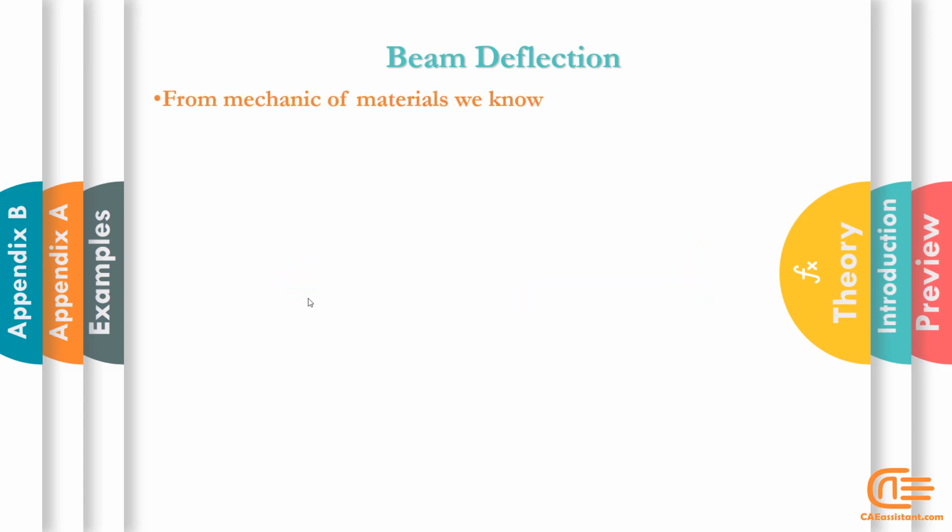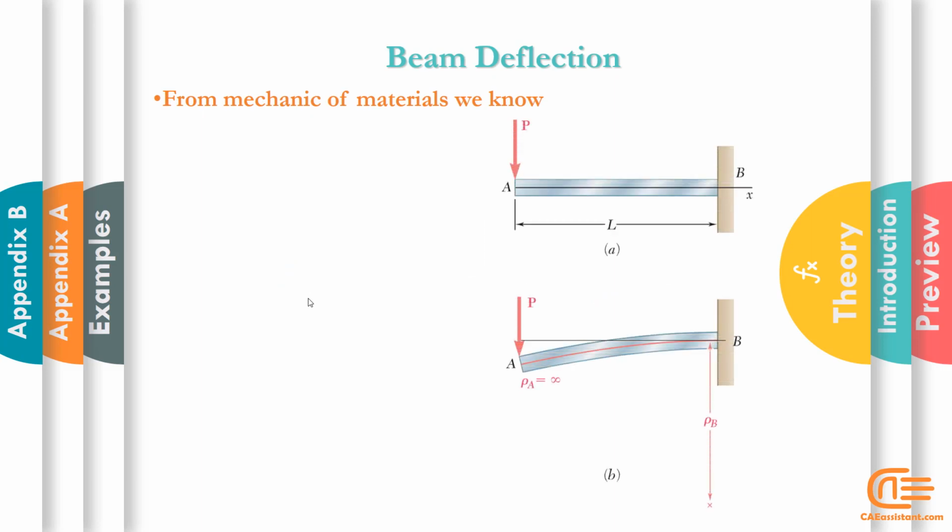The deformation of a member caused by the bending moment M is measured by the curvature of the neutral surface. The curvature is defined as the reciprocal of the radius of curvature ρ and can be obtained from this equation. If you remember, this equation derives from substituting Hooke's law in the strain equation relative to the radius of curvature of the beam, which itself derives from geometrical relations.